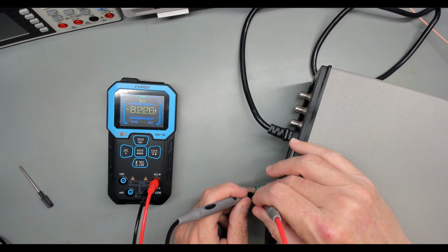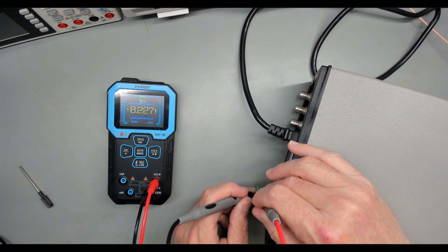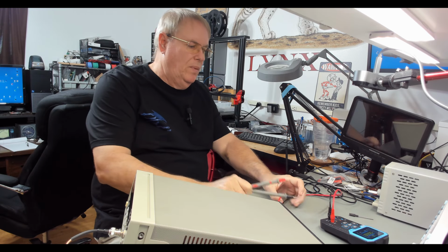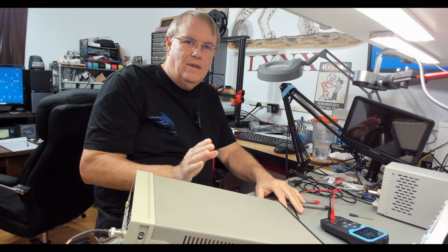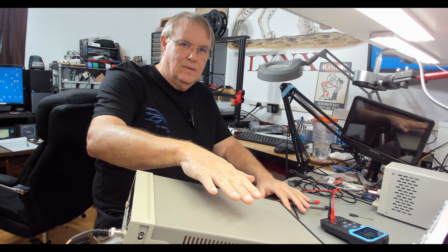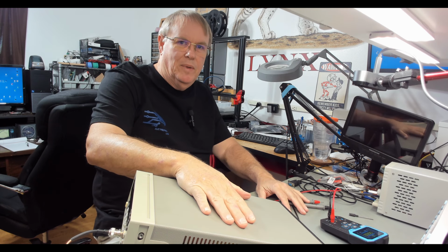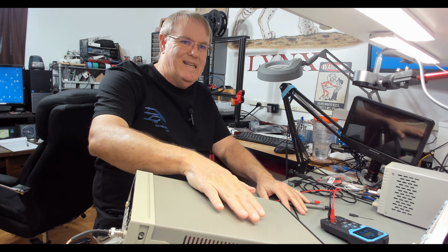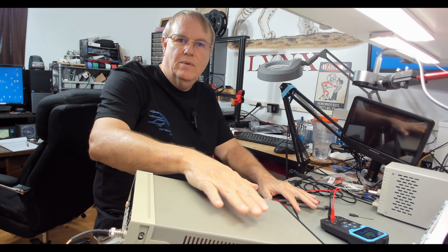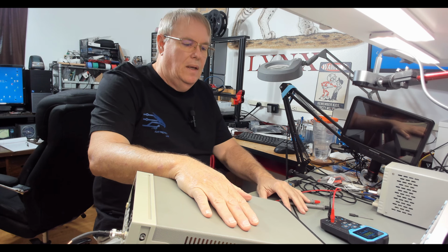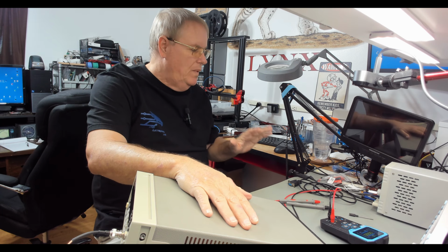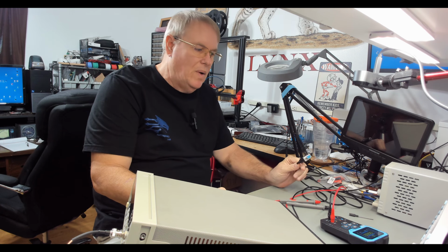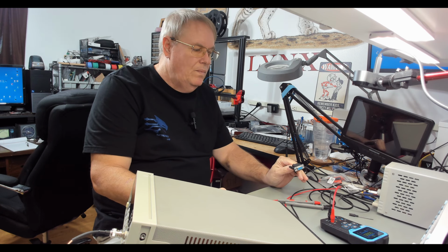Okay, I've got a minus 8.227 voltage. Because I work with COM ports and design some equipment with COM ports, what that tells me is this is a DCE piece of equipment. Since computer ports tended to be DTE, your PC was always a DTE port, that tells me the USB converter is going to represent a DTE.